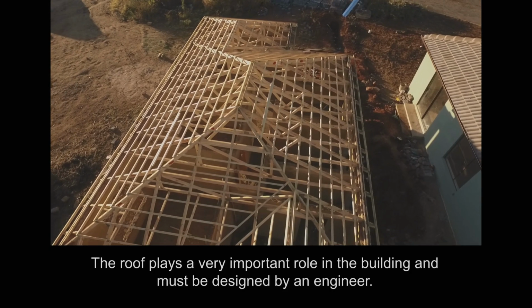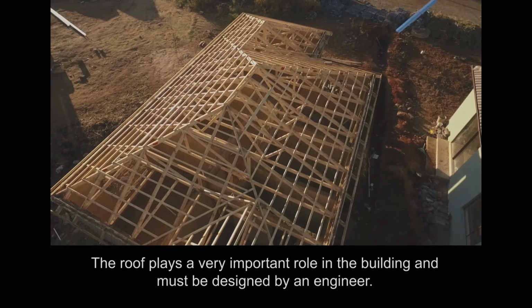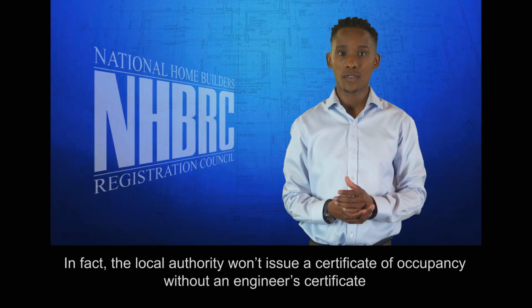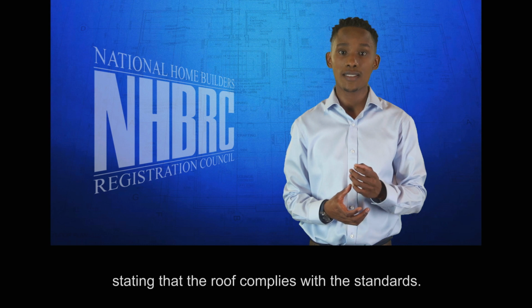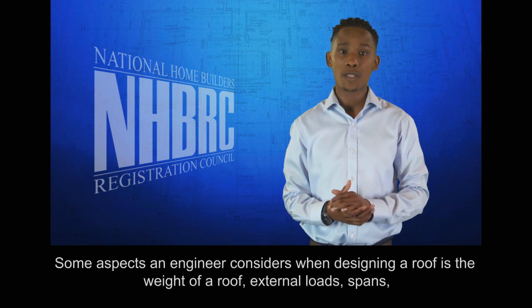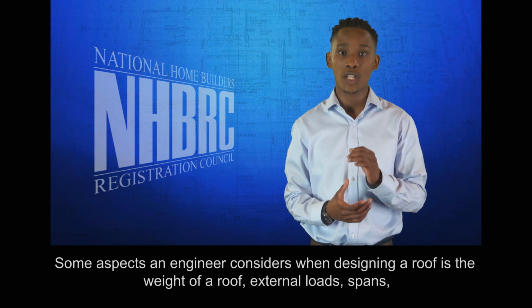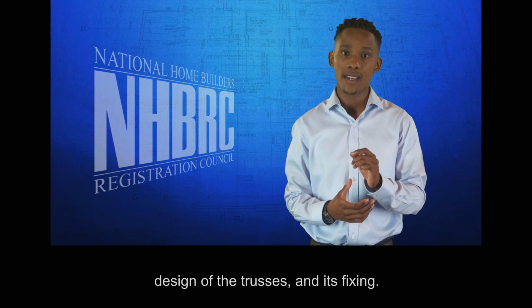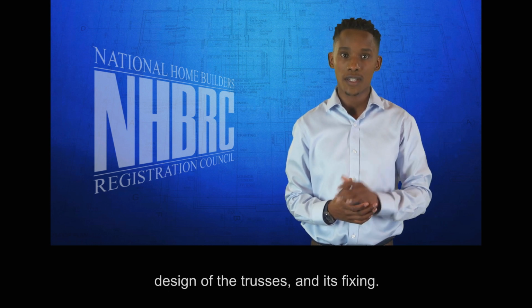The roof plays a very important role in the building and must be designed by an engineer. In fact, the local authority won't issue a certificate of occupancy without an engineer's certificate stating that the roof complies with the standards. Some aspects an engineer considers when designing a roof is the weight of a roof, external loads, spans, design of the trusses, and its fixing.